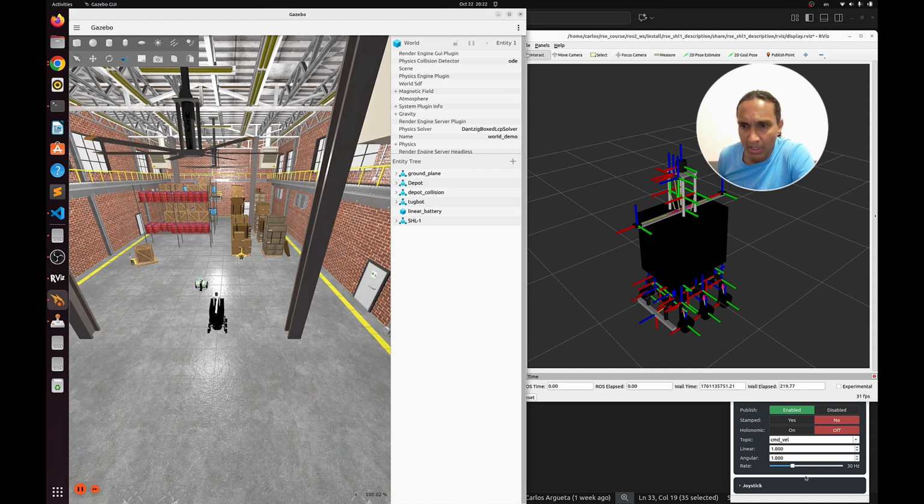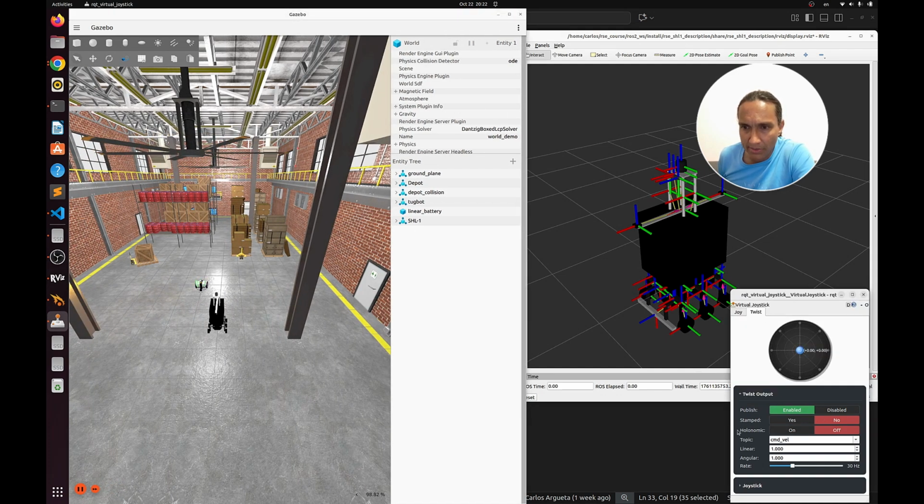There you go. Okay, so non-holonomic way, right? Standard motion, like a standard little car. Look, it's moving. I don't need to launch that Python code anymore. We have a proper ROS2 control plugin that is doing all the computation, all the inverse kinematics computations, and directly interfacing with the joints.